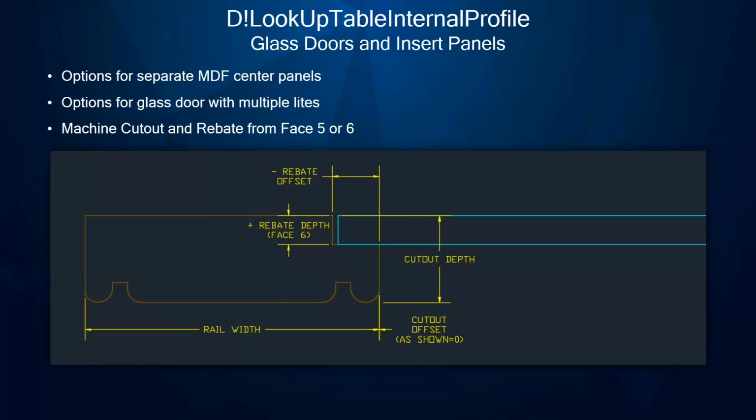And so depending on what you select in the options, you can set that out, and you can machine that cutout either from phase 5 or phase 6. So if you do have a slot cutter that you want to run around on the surface of the bed to clean that out, then you can do that. You just want to make sure that your priorities are set correctly so that you do the cutout first and then the slot cutter after the fact.